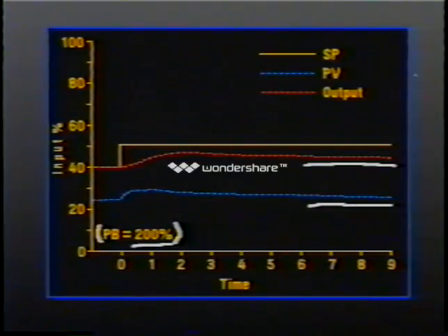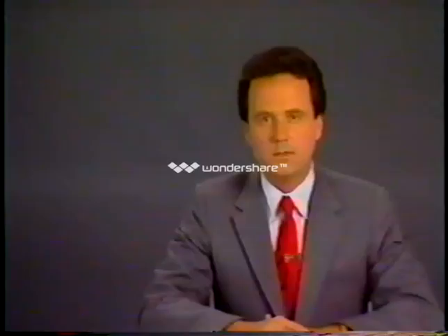However, the gain is so low that the controller only increased 5% for a set point change of 10%, and the process variable hit a new steady state considerably under its set point. Since there is no further change in error, this error will continue indefinitely.